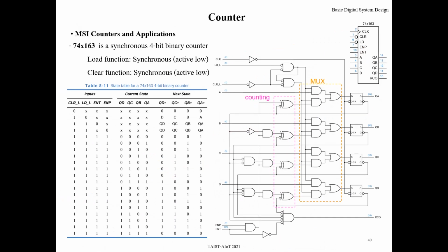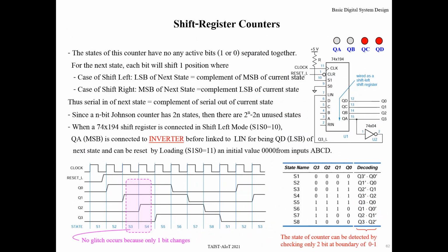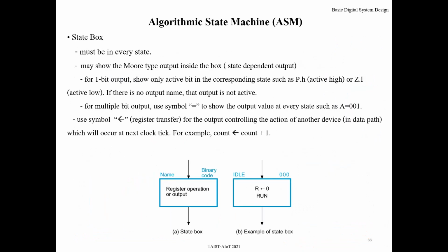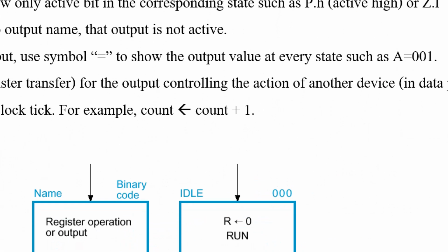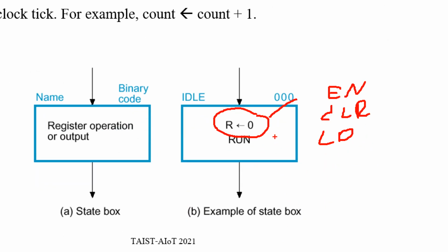So for this one, just apply a signal like enable, clear, or load into the counter or register. But the value is not cleared or loaded immediately. It must wait for the clock tick. This point is very important.